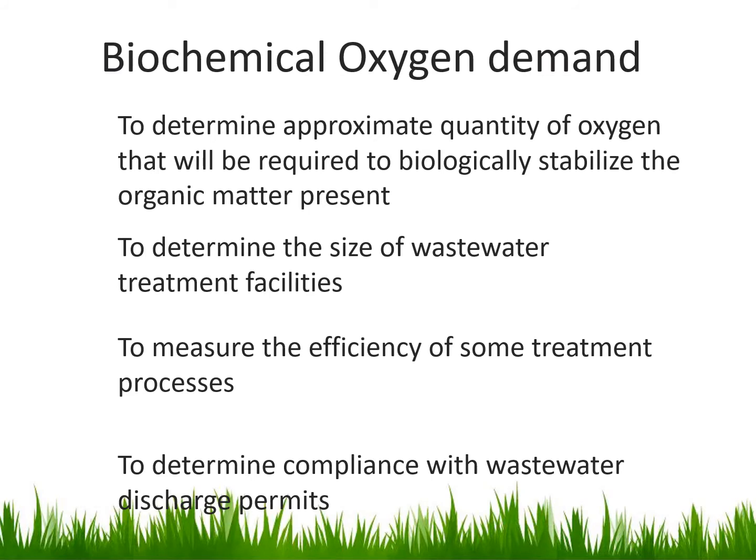And it is to determine the approximate quantity of oxygen that will be required to biologically stabilize the organic matter present, to determine the size of wastewater treatment facilities, to measure the efficiency of treatment, and to determine compliance with wastewater permits. Very simple, go through.